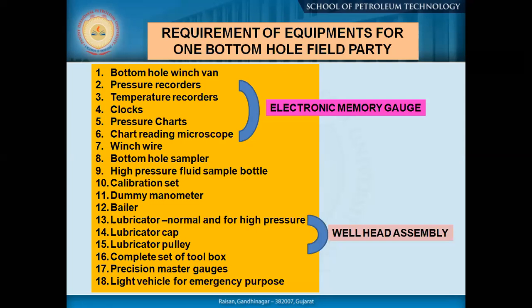Yes, there are different types of well testing. You can see this is the flowing bottom hole study, and we can do the static bottom hole study. I will come to it one by one. Once we lower down the instrument, these are your different requirements you need to carry with you when you go for the bottom hole operation. So the bottom hole winch van, this is actually a truck.